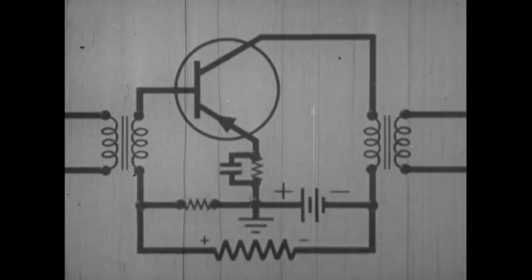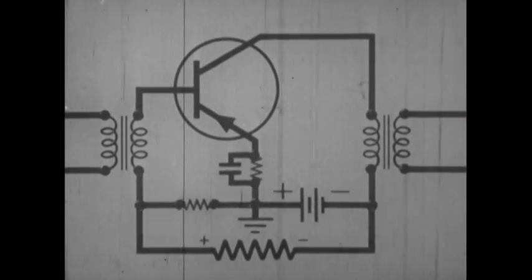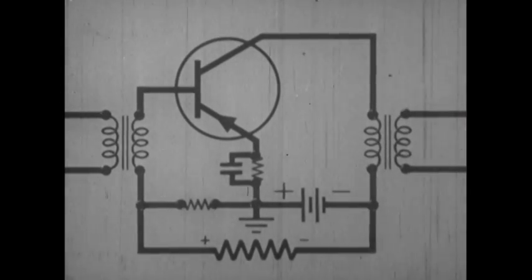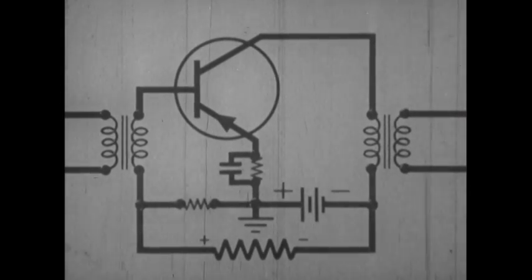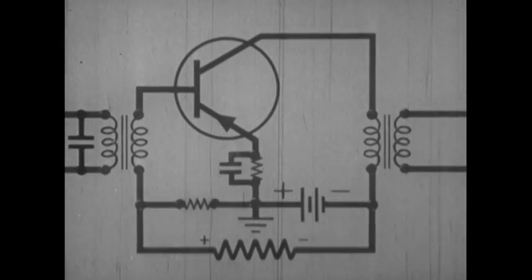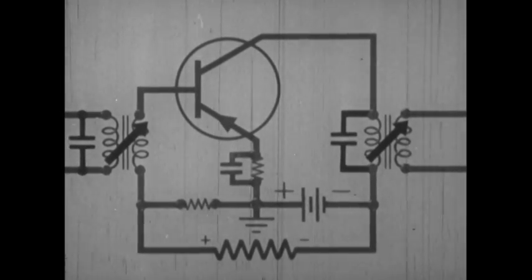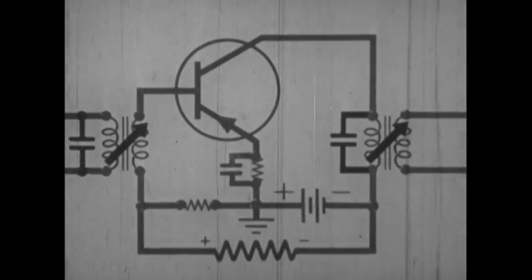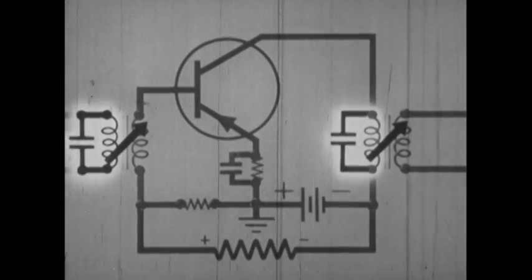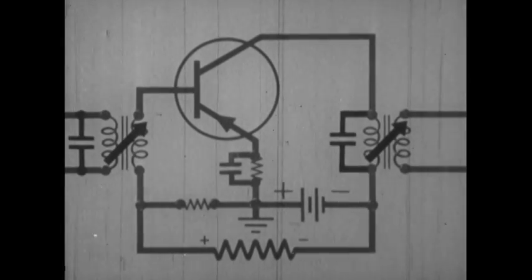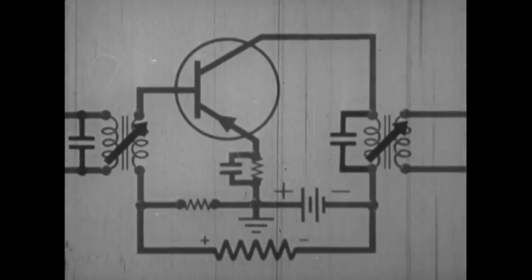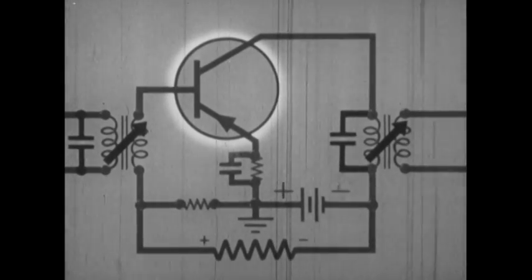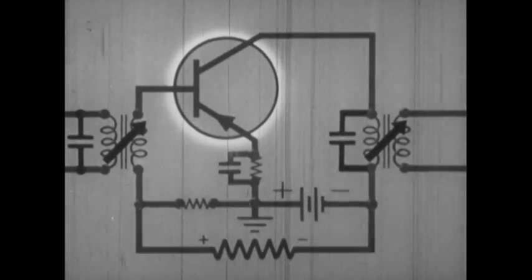This is the schematic diagram of a common emitter transistor amplifier. It might be either a low-frequency amplifier or a tuned high-frequency amplifier. The actual frequency is established by the resonant circuits, but the amplifier cannot function efficiently above the effective frequency limit of the transistor used. This film shows why.